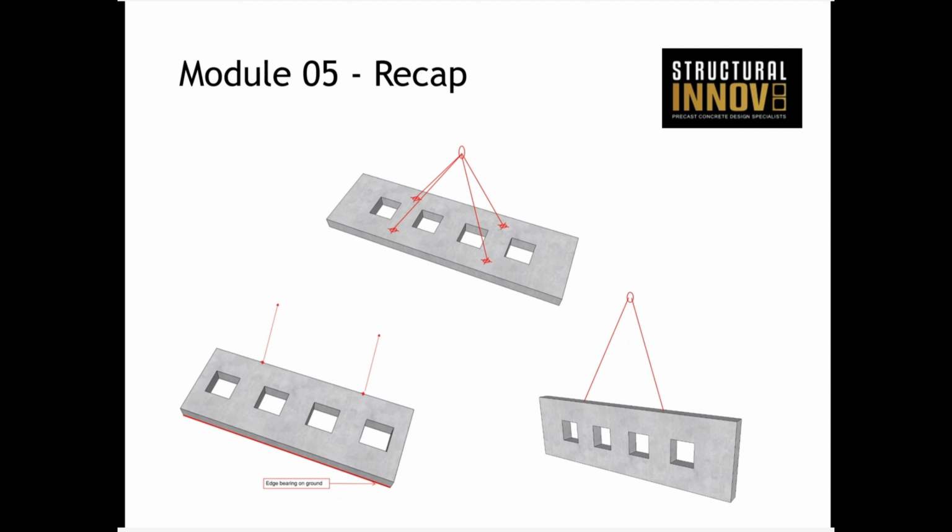We had to think about what we could change. And as I said, there are a number of different parameters: the number of lifters, whether we're going to use a spreader beam, can you afford to leave the unit in the mould longer to get a higher concrete strength, the positioning, additional rebar that can get added in. So there's a number of items like that that can be addressed.